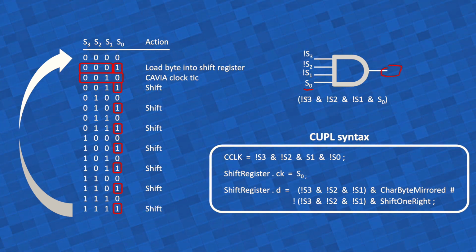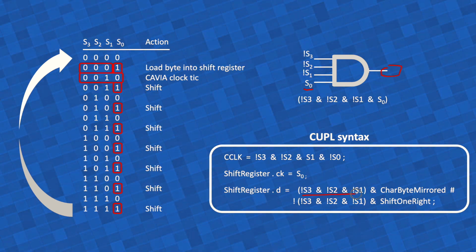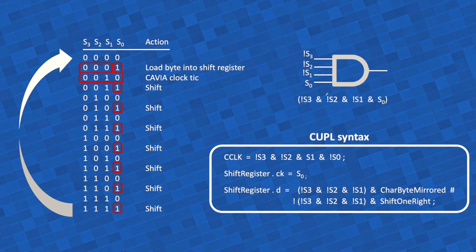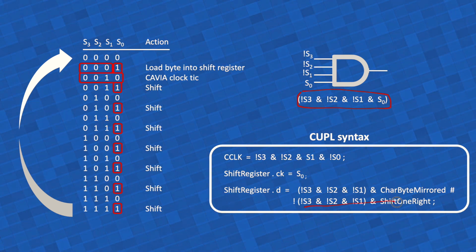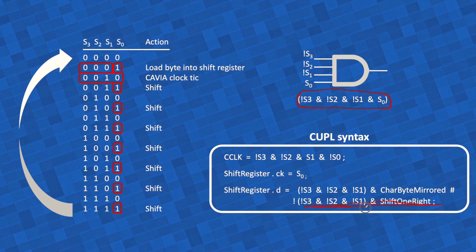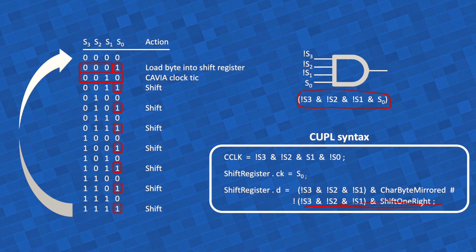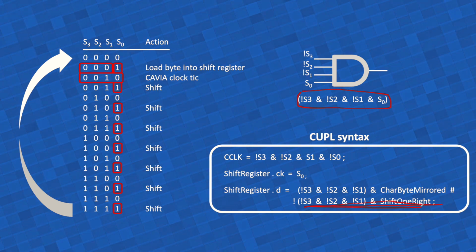So in fact, when you latch the input at S0, this term will not yet be true. Therefore, you will shift, even when you're supposed to load, you will shift. So you have a shift register that will shift everything always and never load anything, so you would get exactly 0 in the video output if you did that.